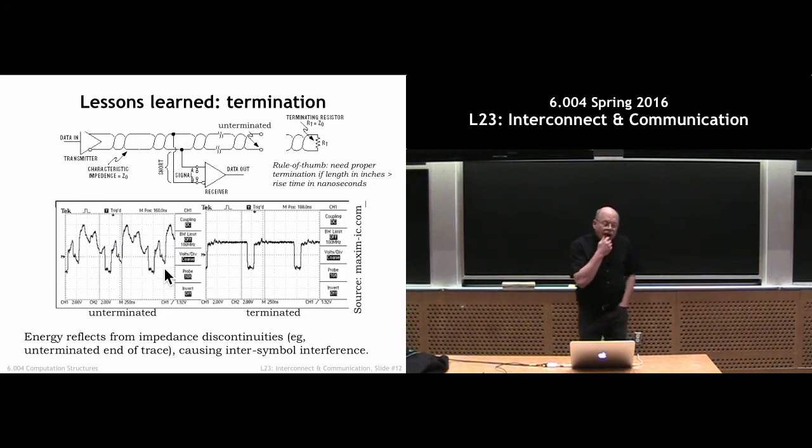The notion, though, is that if you put a signal on and change the relative voltage of those wires, and you don't terminate it at all at the end, you get these awful echoes. So this is a signal that's supposed to look a lot like that, but ends up looking like that unterminated. If, however, you put the correct termination, which is a very fancy word for a resistor, that sits here. You can get active termination, you can get more complicated termination, but for most of what we do, it's a simple resistor termination.